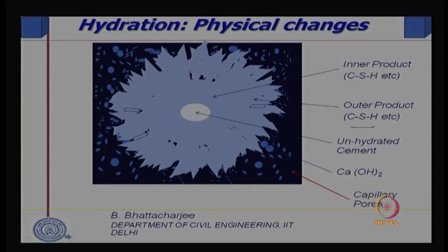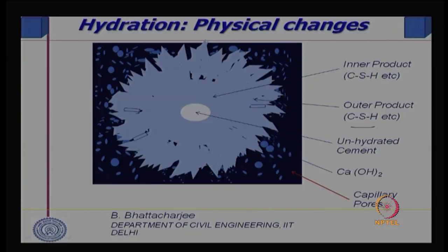So, that is what we call capillary pores; their sizes are large and therefore we call them capillary pores. This diagram explains the process of hydration, taking an idealized cement particle surrounded by water. Now, all the solids that touch each other at some corner or somewhere form the solid skeleton, with another particle touching from the other side, and so on.